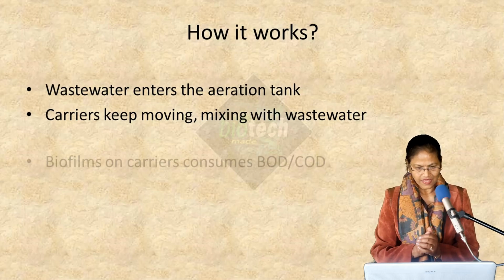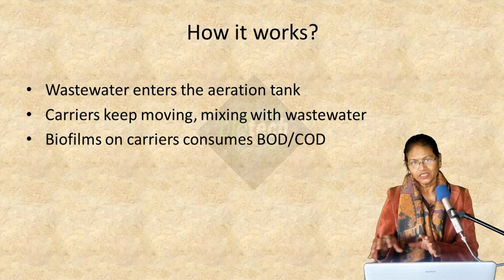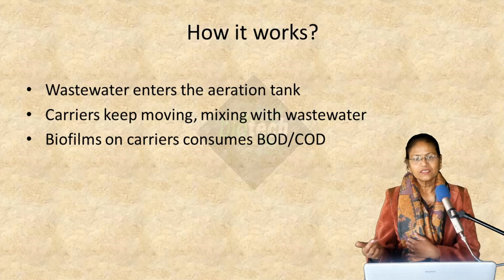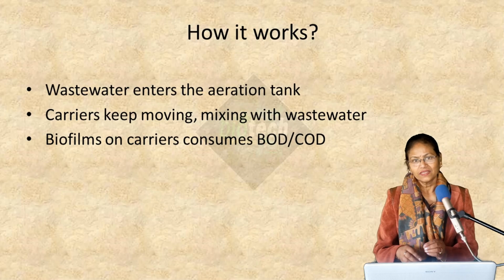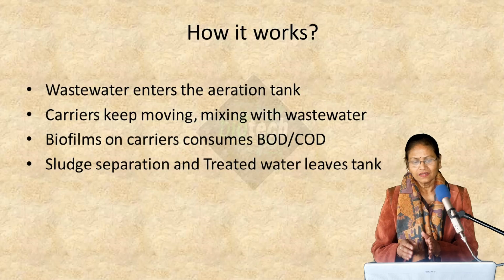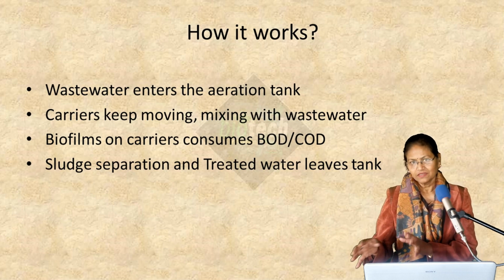So that is what is happening in the aeration tank, and biofilms are present on the carrier. They are degrading, consuming the organic matter which is present in the wastewater, and they are consuming the BOD, COD, which is the indicator of how much oxygen has been used by the microorganisms for the degradation. And the sludge separation is also possible here. It takes place here. And the treated water leaves the tank, and the sludge separation all takes place